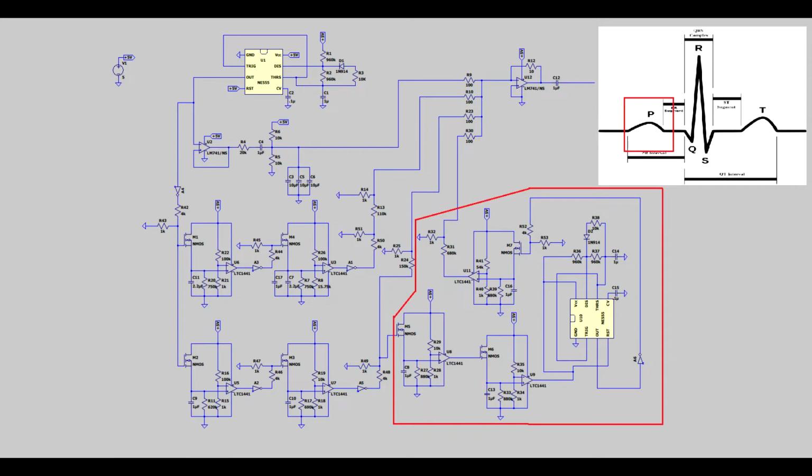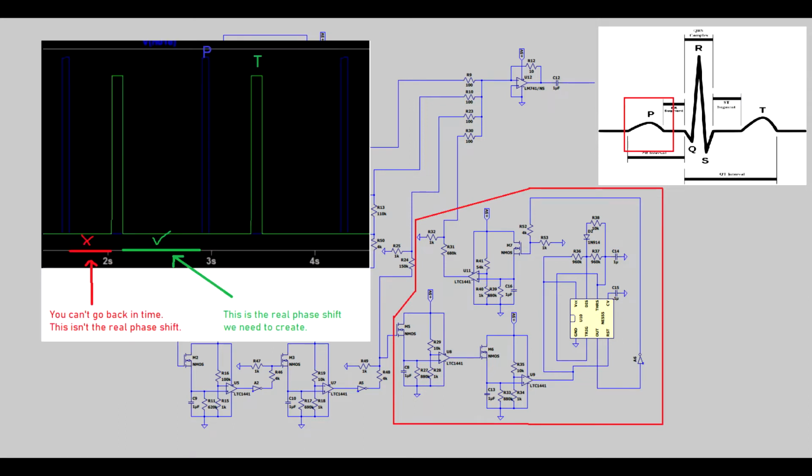The circuit generating the T component is very similar and works based on the same principles. The P component was the hardest to produce due to high phase shift relative to the signal generated by the first 555 timer. It turned out that 3 delaying circuits and another 555 timer were needed to obtain a signal with appropriate phase shift.